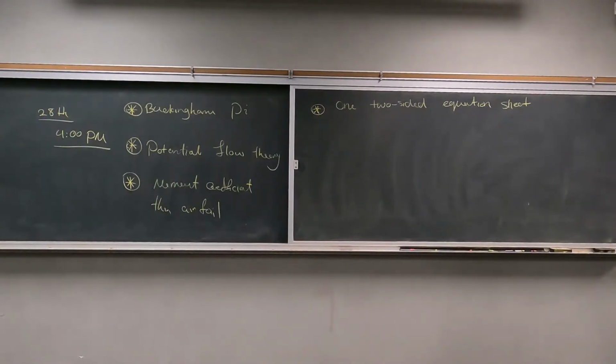For lift coefficient, it is usually presented with CL versus alpha. For drag coefficient, it's usually presented with a drag polar, which is CL versus CD. How much drag you're going to get while you produce this much lift, right? They don't have any way of calculating lift using that setup. That was the only thing they could do.